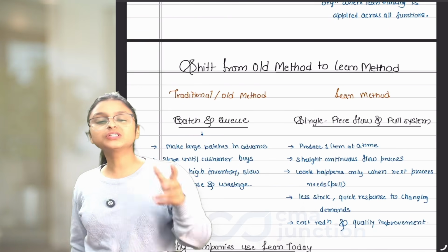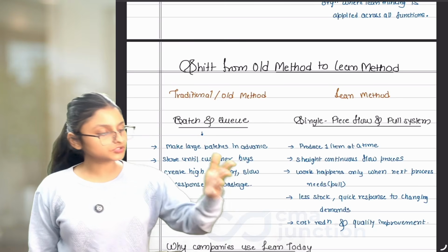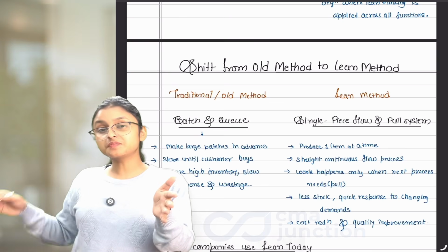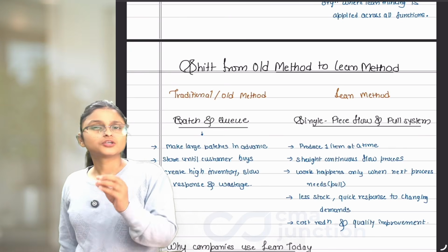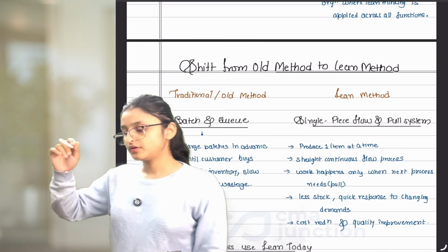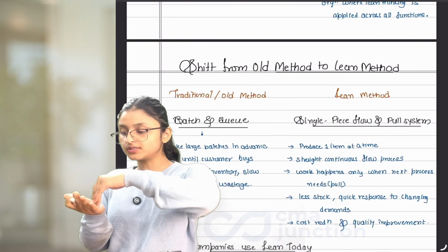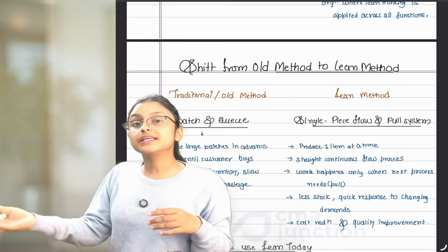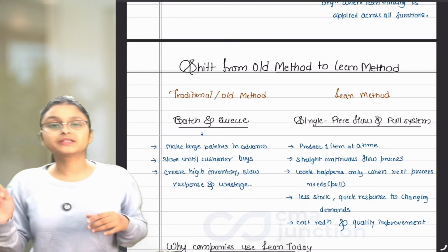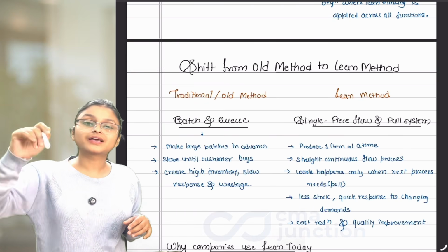Think about it, how much time is wasted. When process A is producing all the 1000 units, process B is waiting at that time. Similarly, when process B is producing, process C is waiting. So a lot of time is wasted. Similarly, think of the final product. Process C also produces all the 1000 units together, and then we get 1000 units of final product all together. Now this final product will be inspected and it can happen that there are defects.